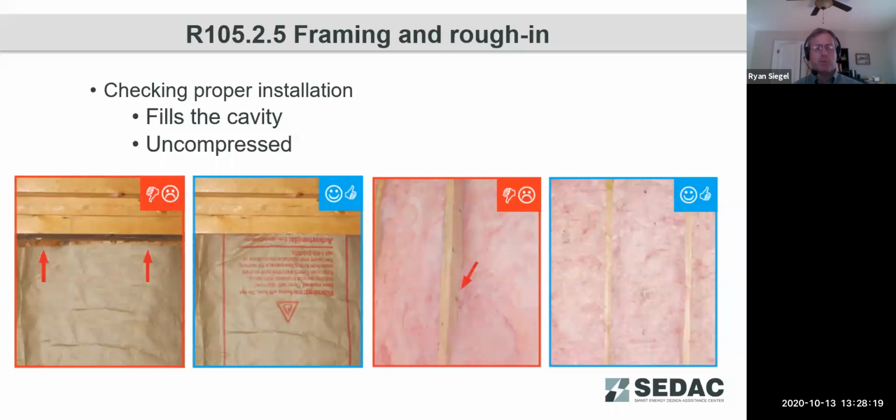However, there's a few problems with side stapling. One is you have the potential air current because now the insulation right by the framing has a pocket of air, so you could have air currents that develop in these spaces. The second is that the vapor retarder no longer overlaps with one another, so your vapor retarder is no longer continuous.